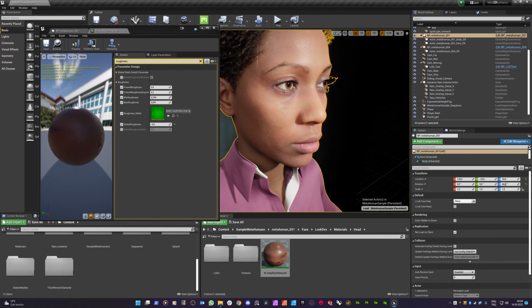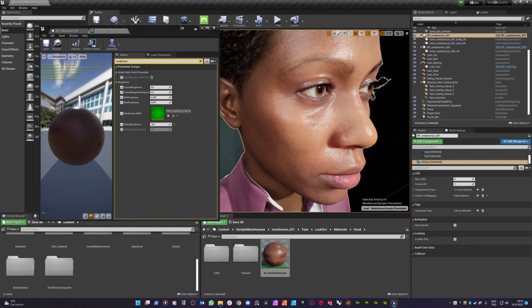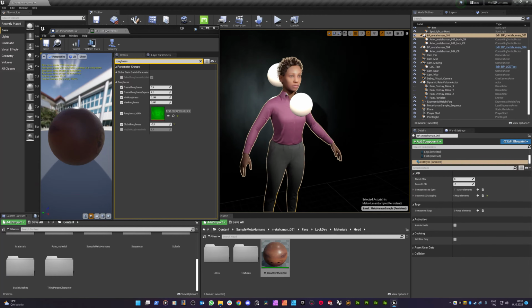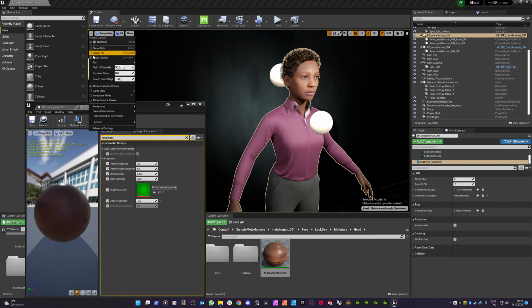Nothing much changes. Let's see the LOD of this Metahuman. I set it to 1 to save some performance or system resources. You see that there is a LOD sync under the blueprints of the Metahumans. The default value of this is -1, so it is affected by the distance, and shows the specific level of detail of the current actor.